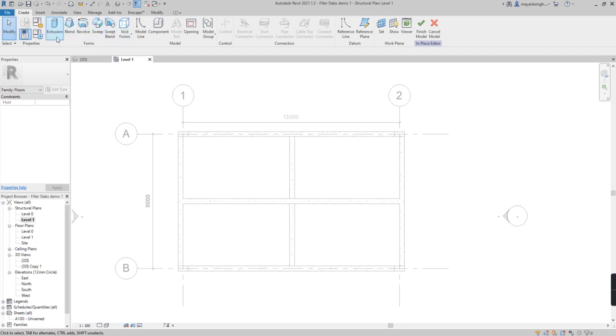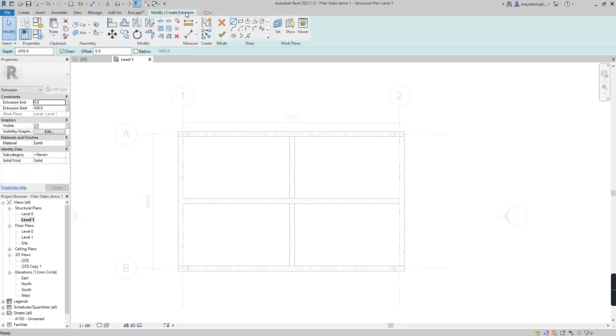We are in model in place mode, and what happens here is you will get a lot of these options, but what we are doing is an extrusion. I'm going to make 4 rectangles and extrude them downwards. I'm making 150, so extrusion, and now another tab opens up, and here you can either use this and model each of these 4 sides, or for me it's simple. I can just use rectangle and make 4 separate rectangles that fill in the space between the beams.